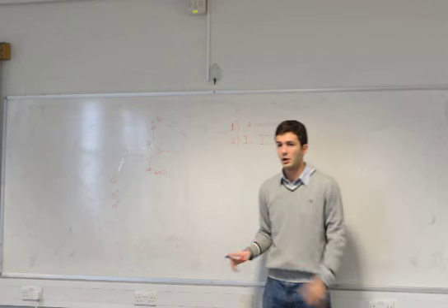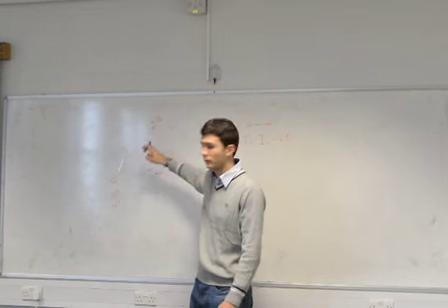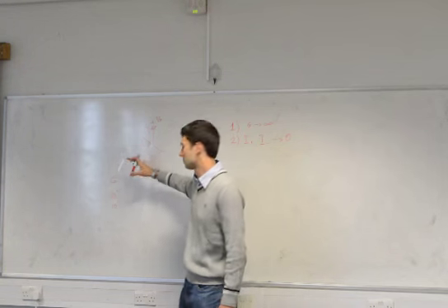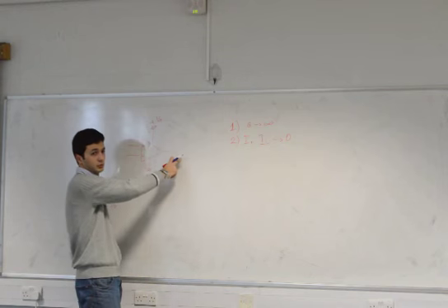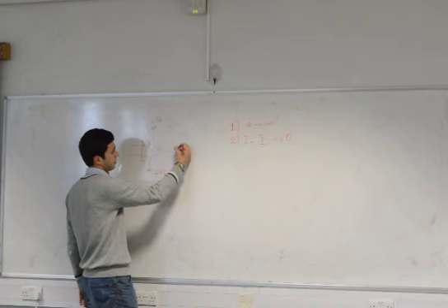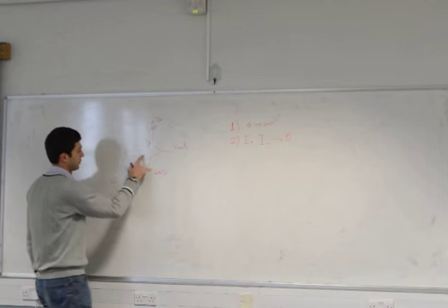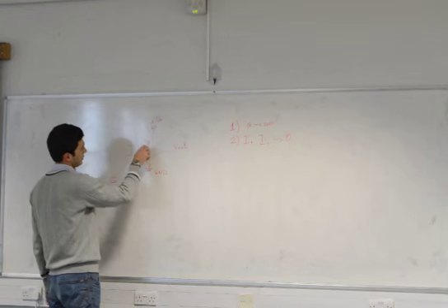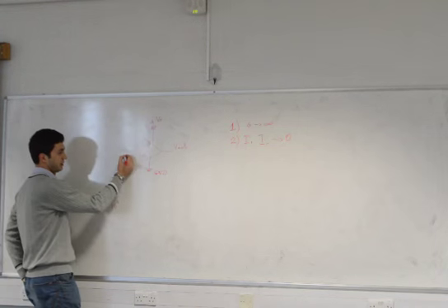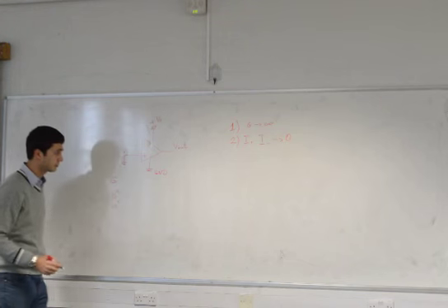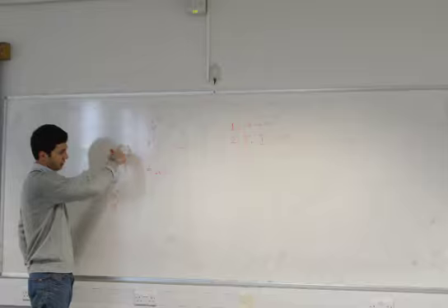No input power. What they do is, when you apply voltage to these two pins, the voltage difference is multiplied by the gain, and you have an output, voltage out. Let me draw this like this. If we connect this pin to the ground and apply voltage here, here's what is being done.